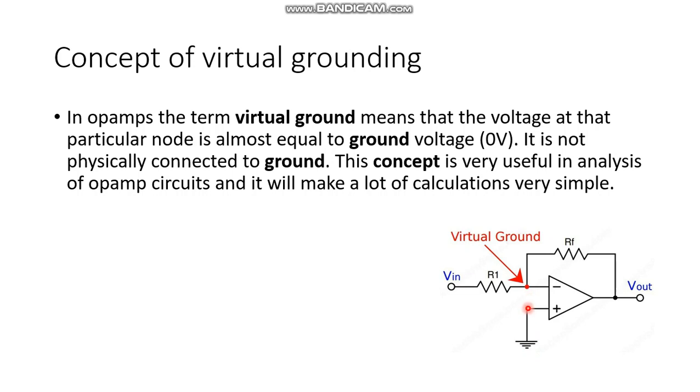If we connect 1 volt here, this also shows 1 volt. Whatever the voltage at this point, the same is reflected at this point. If I am grounding here, this is the physical ground and this is a virtual ground. The same voltage appears here.